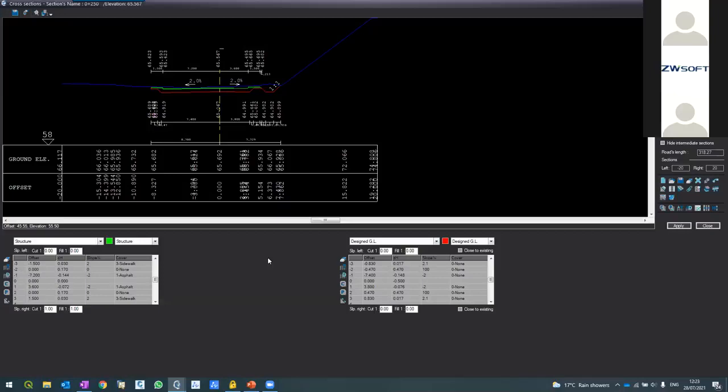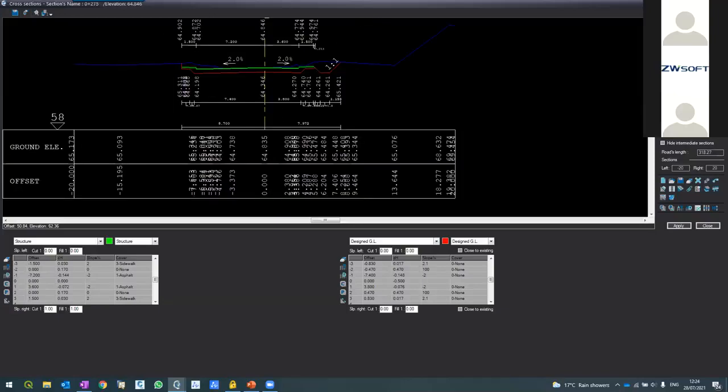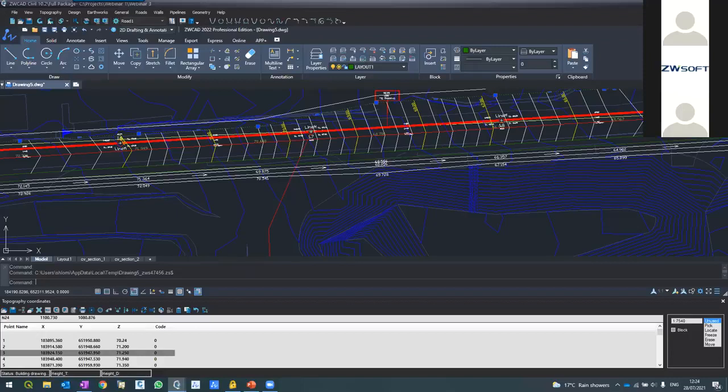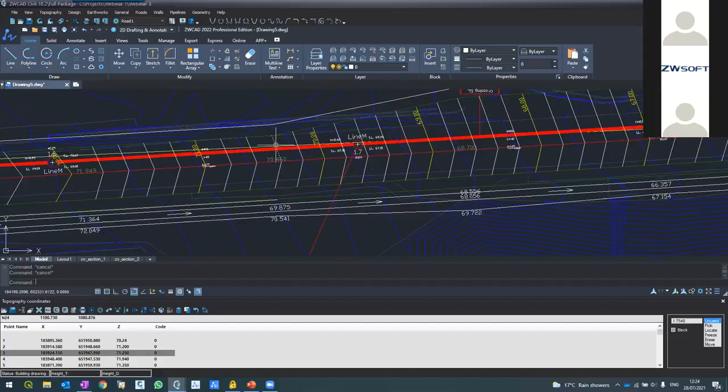I changed the template to be wider, starting from 200. So I have the same corridor, but with different lengths. Of course, I can split it into two different corridors, but then I will need to create a link between them, which is more complicated. It will not be unified.